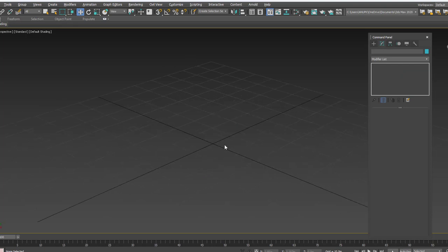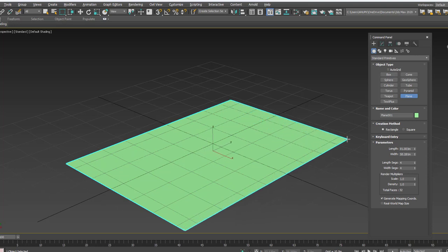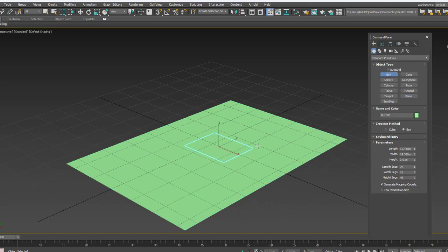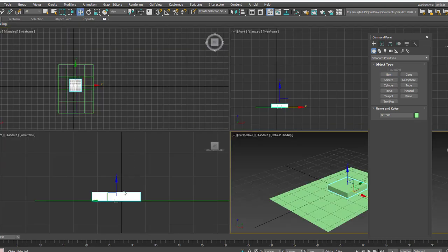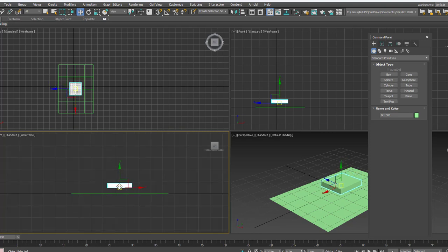Next one is cloth modifier. In order to make pillow, curtain, tablecloth, normally we use this cloth modifier. Let's work with that. For that I just draw the plane and then box. I just keep this box just above the plane a little, keeping it center.